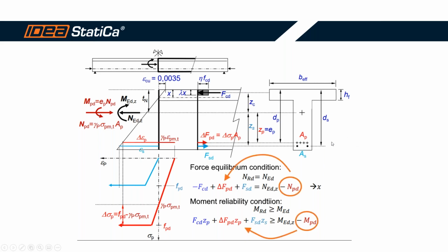In IDEA StatiCa, there is a small difference, let's say, that you will find the primary effects of pre-stressing on the left part of the equations. So it means that we add the contribution of the pre-stressing to the side of resistance of the section.